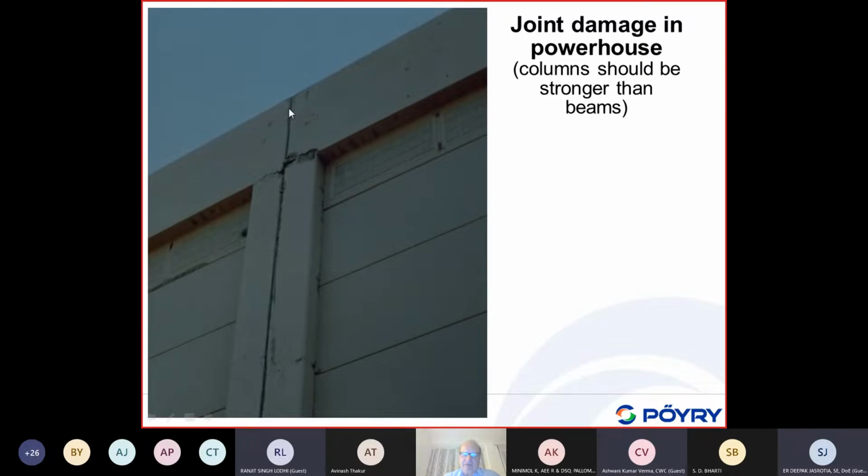Downstream, you see here the joint between units. This is a typical structural problem: we have a plastic hinge here at the end of the columns when we have a very stiff cross beam. For seismic safety, this failure mode is not good. It should be the opposite. We would usually design structures so that plastic hinges develop in beams and should not develop in columns. These are dangerous.